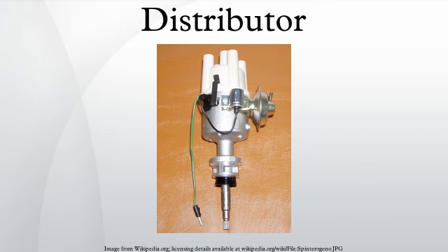Spark plug wires, which need routine replacement due to wear, are also eliminated when the individual coils are mounted directly on top of each plug, since the power is transported a very short distance from the coil to the plug.